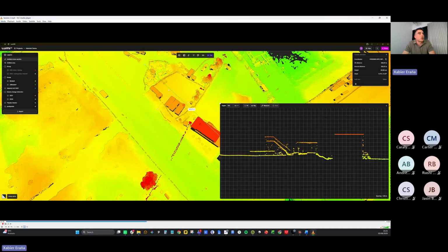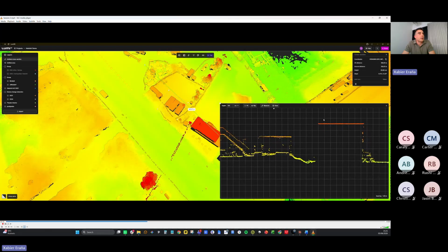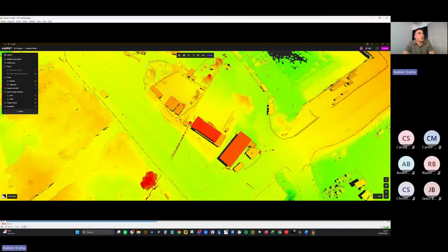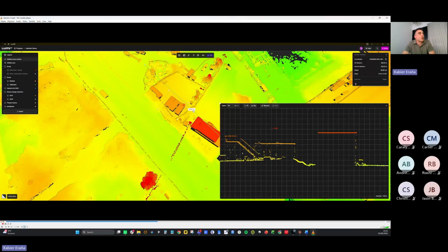There we see a cross section. I can give a depth according to the specific need, and there I make a measurement of that particular building, also of the staircase and the angle, and the different measurements are computed automatically. I'll clean that out. You see how easy it is to make a cross section.